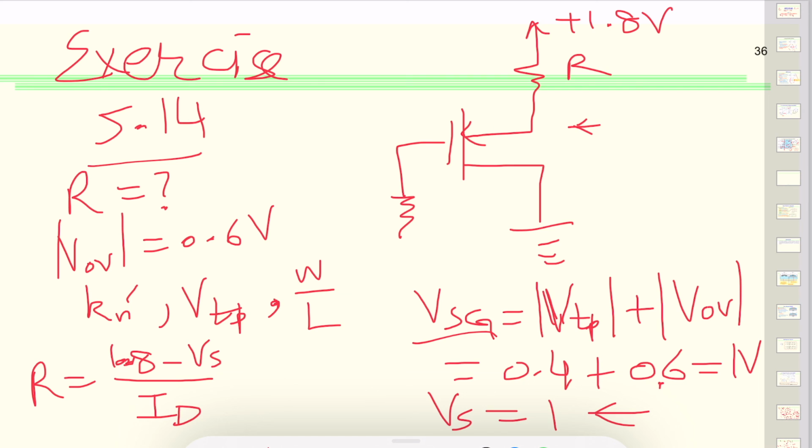From this we see that the drain to gate voltage is 0 because both of these are grounded. So in that case, we can see that the transistor is operating in saturation, where the drain voltage is definitely at a higher level.